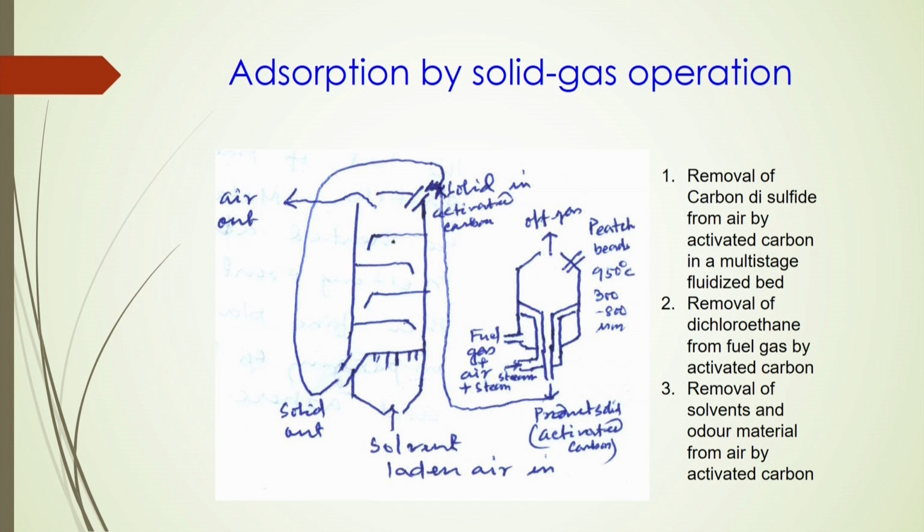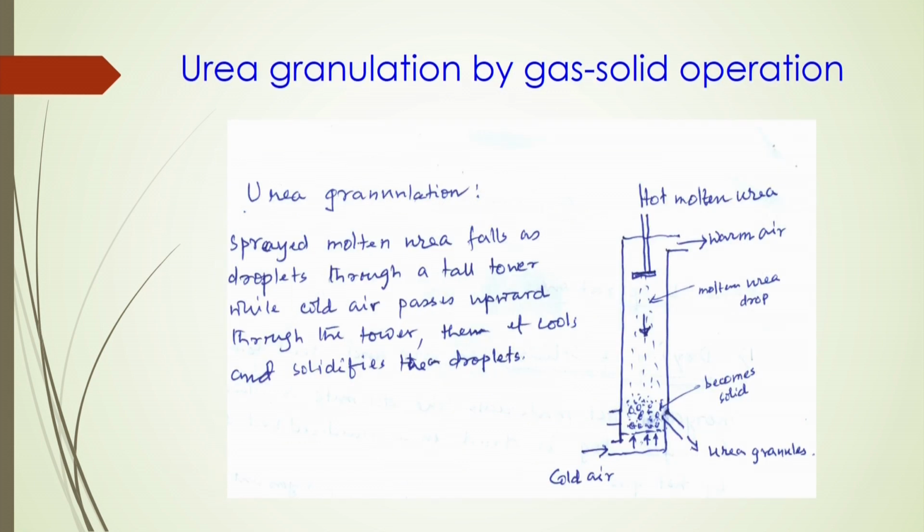Even removal of dichloroethane from the fuel gas you can also do in the presence of activated carbon in the fluidized bed operation system of gas solid operation. Even removal of solvents and odorous materials from air by activated carbon can also be done just by fluidizing the activated carbon particles by air. So, these are the physical applications of this gas solid operation.